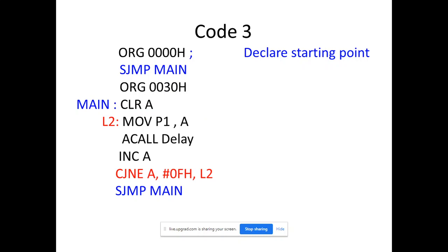just displaying a hex counter. Suppose in the university exam, instead of a hex counter, they make a change and want a BCD counter. At that time you just make a small change within this program. In a BCD counter we want to display a number from 0 to 9, not 0 to F, and in that case I will change only one parameter here. All other program remains as it is. The only change is that here instead of 0F I am writing 0A.